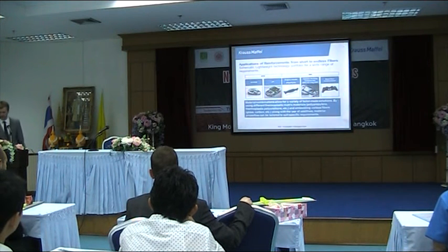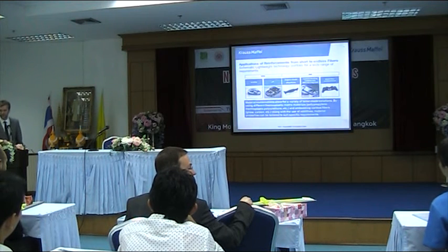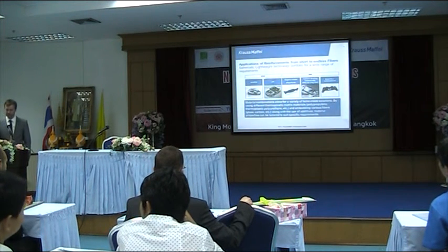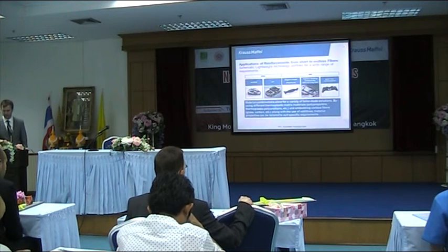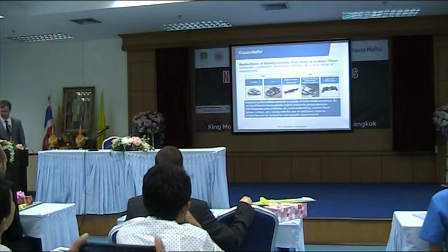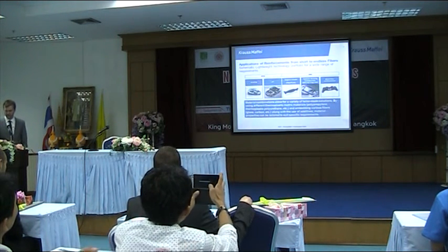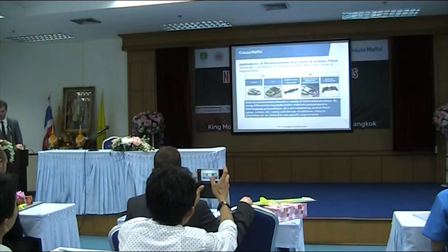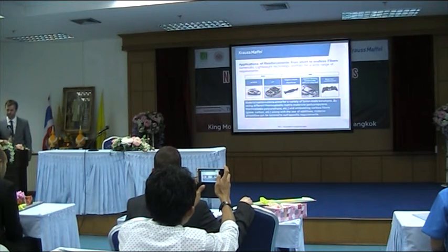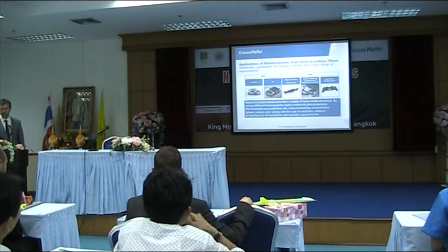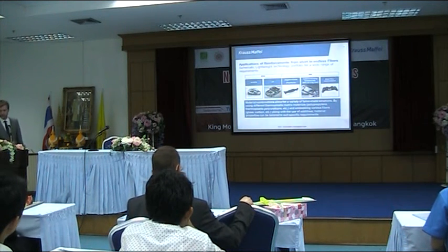So material combinations allow for a variety of tailor-made solutions. I think this is one of the key issues. By using different thermoplastic matrix materials, for example polypropylene or thermoplastic polyurethane, and embedding various fibers, glass fibers, carbon fibers, and so on, along with the use of additives, material properties can be custom tailored to suit specific requirements. And I think this is very important for all future technologies.